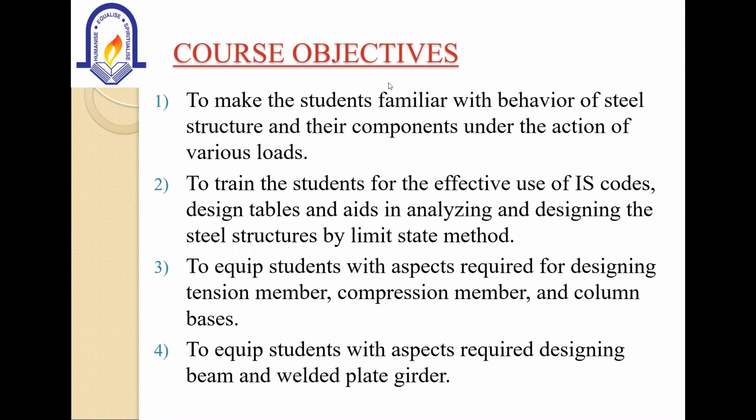The particular values in the IS code are what you are going to use for the designing purpose. So you are going to refer to IS code 800 2007, whatever the formulas, whatever the tables, and whatever the particular values are there in the IS code. You are going to use that only for the design purpose.